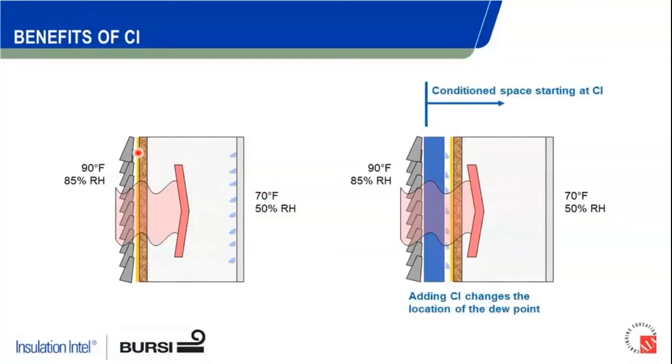So if you're under these conditions for a significant period of time, or a warm climate where we're under these conditions the majority, 6 plus, 9 months of the year, I would recommend putting some type of capillary break in this layer of the wall system, right? Because we know we're going to risk condensation here.